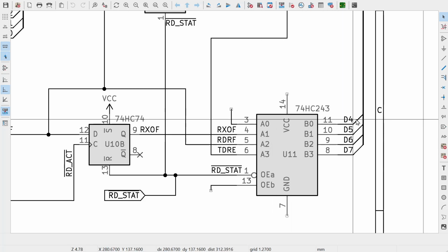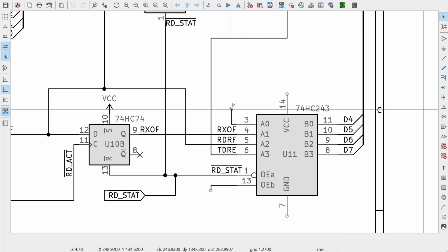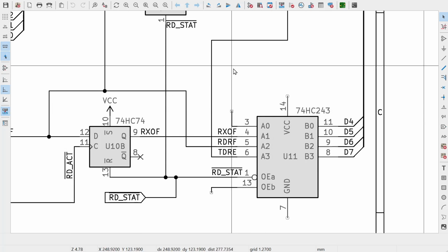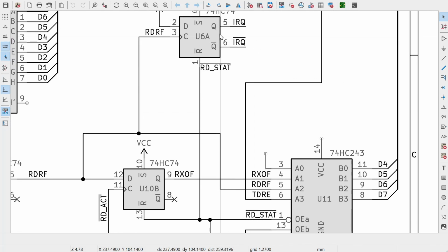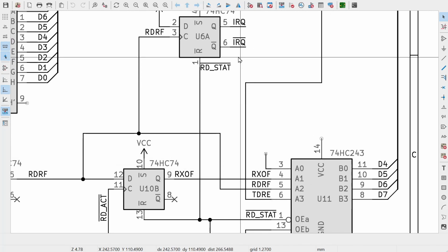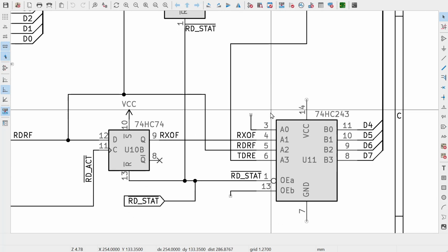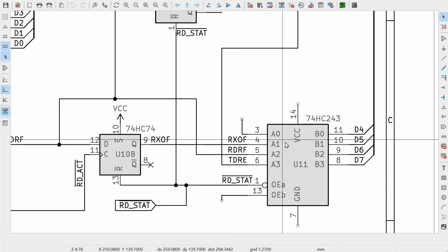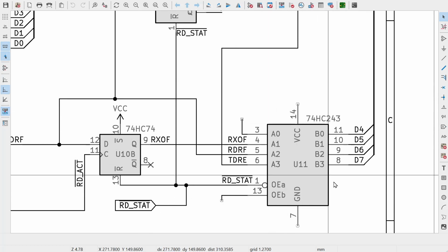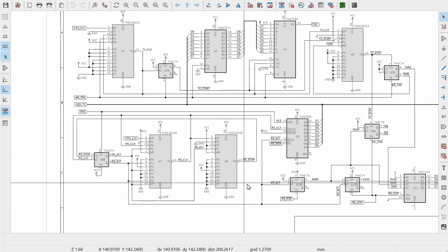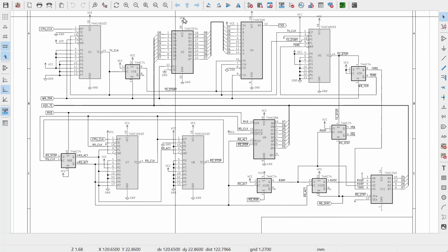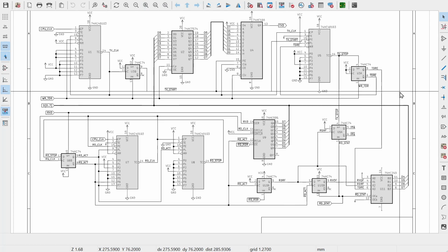Bit 4 here I have just wired high. I haven't marked it on the diagram properly, but I think I just didn't have anything interesting to put on that one yet. One option might be to connect it to IRQ, for example, so then the CPU could actually proactively ask whether there was an interrupt waiting, but that's a bit weird because it's going to get cleared as soon as you read the register and stuff. It's a possibility. Haven't really thought about that one in detail. Anyway, that's the run through of the new parts of the circuit for receiving serial data. It's very similar in principle to the way the transmit circuit at the top works.